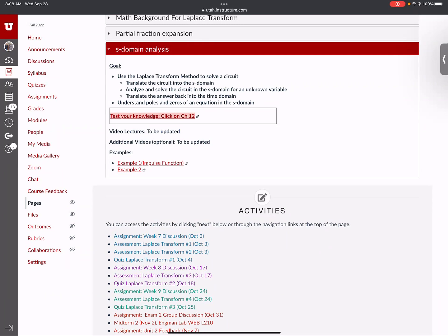But now you can have input sources that are more than just a constant or a sinusoid. It can be a complex input with multiple ups and downs or ramps or whatever signal. Plus we can now handle more than just two components of an L or a C. We can do LLC, we can do fifth order, meaning five of those elements in a circuit, using these techniques. So that's where we are. Any questions so far?